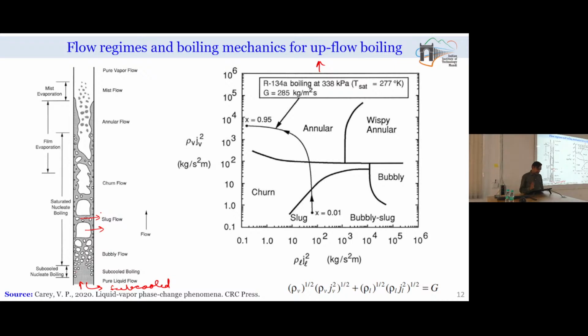And in this process, one important point is that the situation is almost symmetric. In a horizontal pipe, the wetting of the periphery of the tube was not complete, but in this case the wetting will be almost full. And again we will get some churn flow and then annular flow and similar regimes. The only difference is that here the wall almost everywhere symmetrically contains a thickness of liquid film.